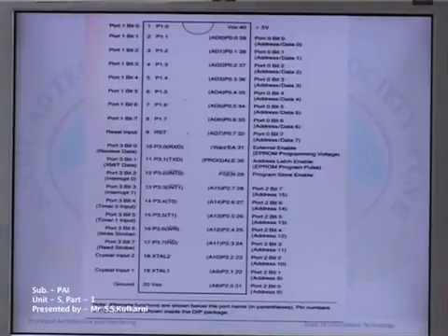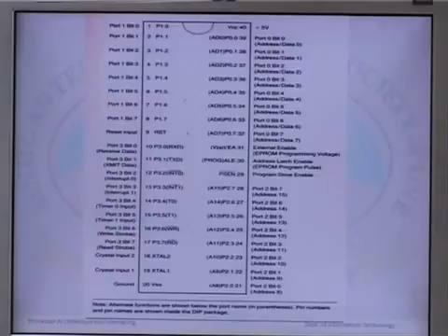Pin number 16 is write bar. Whenever write to the external RAM, that is additional RAM, is performed, this pin is activated. Pin number 17 is read, RD, that is nothing but read. So whenever the data is read from external RAM, this pin is activated.